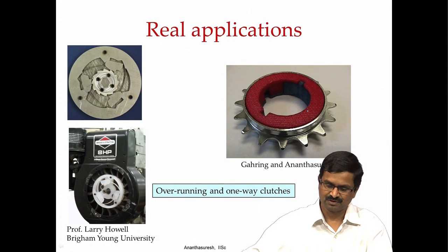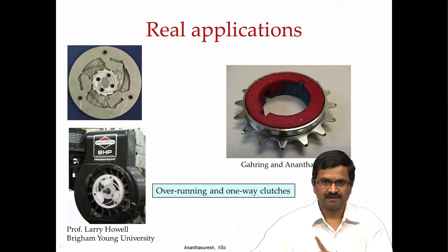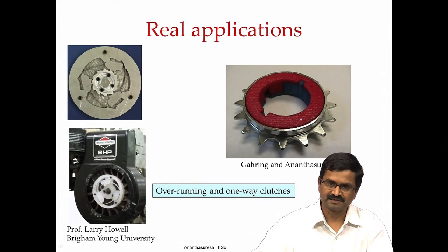If you take apart one of those, where I have the chain sprocket wheel still visible here, there will be many parts. Instead of that, you can have basically two compliant pieces. There is a red color, underneath that there is a blue color, and that basically has like a compliant pawl or ratchet, which will make it go only one way and not the other way in terms of transmitting the torque. So, they are all real applications that one can use in appliances and devices.